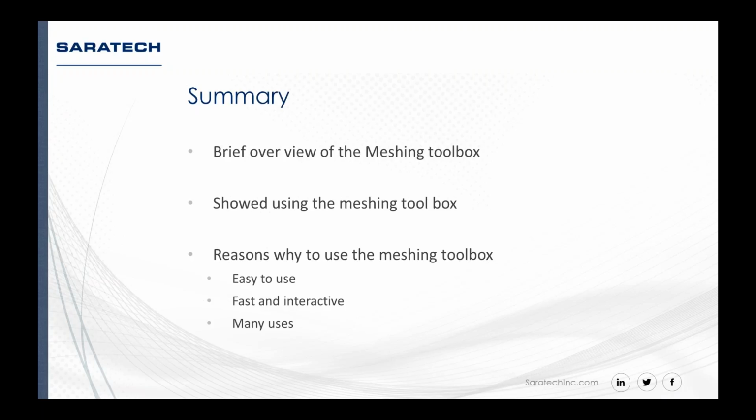Okay, so let me give a brief summary of what I went over. I showed you how to use some of the features in the meshing toolbox. I tried to cover everything, and we only had about 30 minutes. I see I went a little bit long. Try to get in there and use it. There are a lot of good things, especially dynamically sizing, creating meshes on the fly, and using some of that feature removal. Because sometimes you go to the delete pull-down and something's not being deleted. A lot of times, if you use the meshing toolbox, those entities will be deleted.